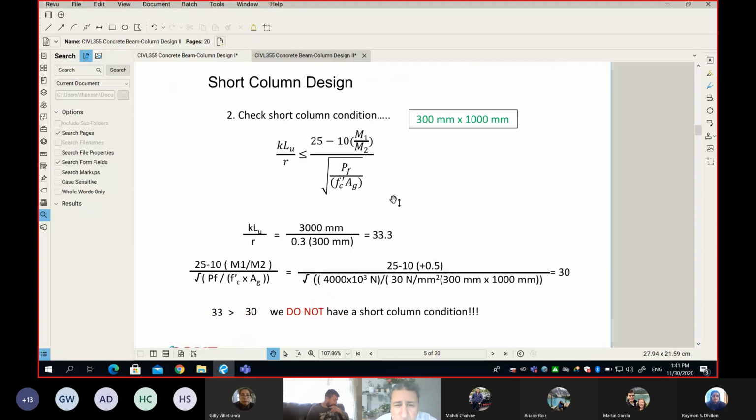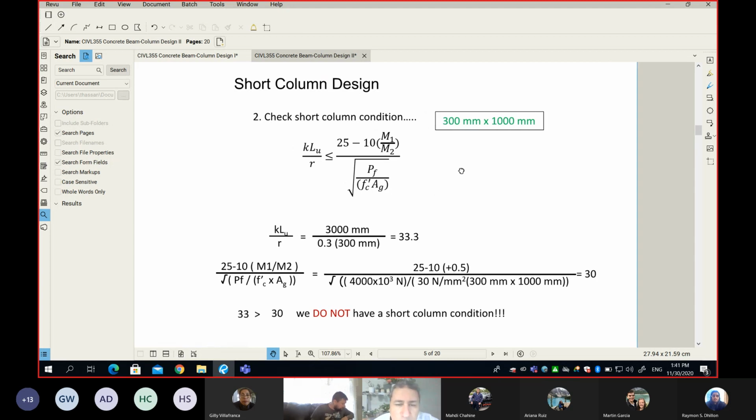So now next, what you have to do before you do anything, make sure that the concrete column dimension meets the requirement for a short column. Because if it's not short column, it means we need to add a more moment due to buckling. And that's what we'll do right now. I will ensure here in this step that my column is a short column based on all the geometry available. Not very difficult. Look at this, please.